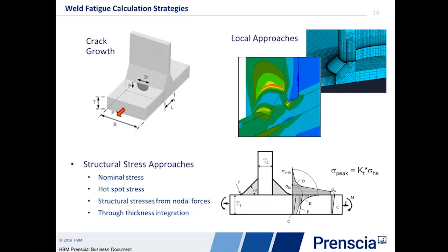Another approach is going off and having some sort of local modeling of the welds. And here, either we will have a refined mesh around the weld itself, maybe in our model, or we will have breakout models that go in and describe the detailed weld behavior and geometry from maybe information from a coarse model, things such as displacements or forces.